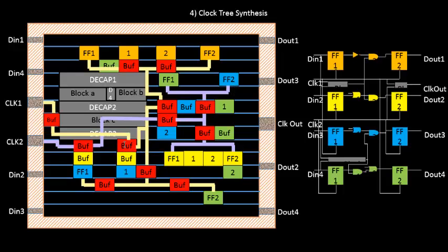We have talked about all this in detail, about the wire length and the number of buffers placed in the path, in a separate course on clock tree synthesis. And the next step, after we are done with clock tree synthesis, is clock net shielding. Clock nets are the most critical nets, and they have to be shielded. They have to be protected from the outside world.